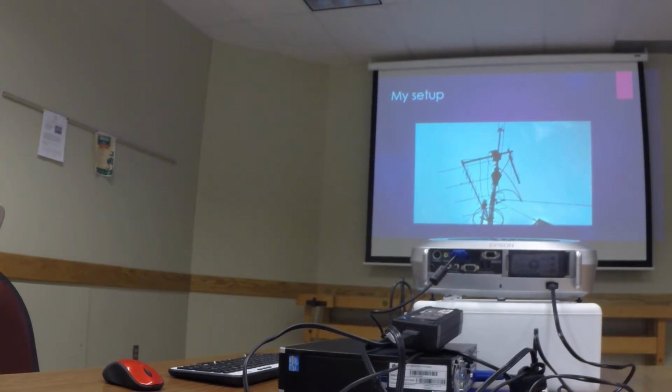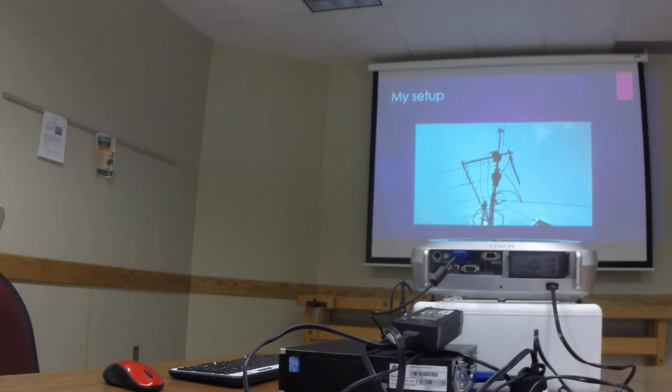Then there are linear transponders, which are like your old UHF TV translators. It's got a band of frequencies, it takes a snapshot of that, and repeats it out. There you can have CW or sideband signals simultaneously. The only problem is that all of the power for the transponder is shared. So if a guy comes in with 500 watts, everybody else is going to go down and you're not going to hear them. There's a lot of careful practice that should be followed not to do that.